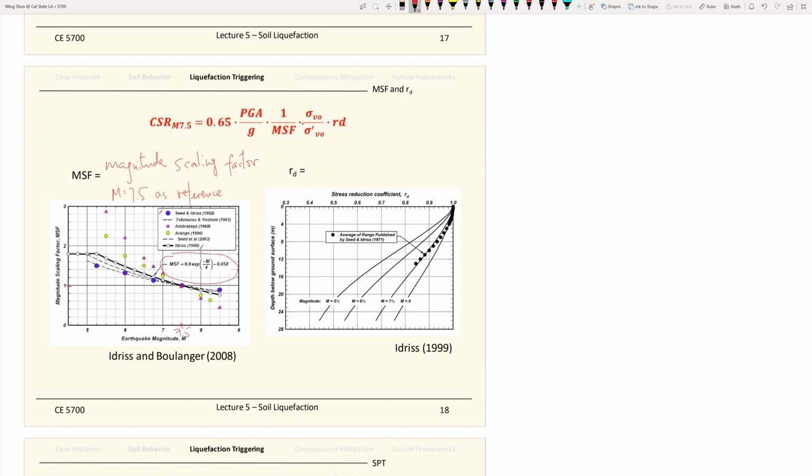Some of the correlations over there are really outdated already, especially the 1988 or the 1983 Japanese one. I don't think anybody will be using those correlations now, because some of them were quite dangerous. Even this Ambraseys 1988 method, you go forever high and go forever low. And this may not be true, especially when you have a very small earthquake and a very large earthquake.